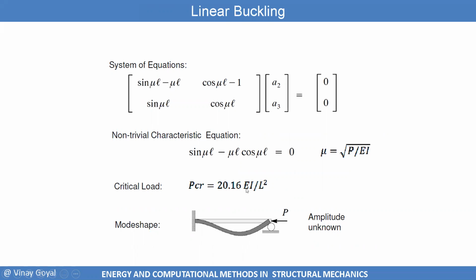And that's the exciting part about buckling, right? It depends only on the material property, the cross section, and the length. The longer the length, the easier to buckle it. The greater the moment of inertia, the harder to buckle it. The greater the modulus, the harder to buckle it. So very interesting here. We're able to find the buckling load.